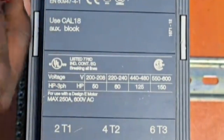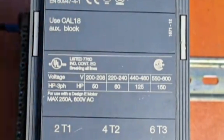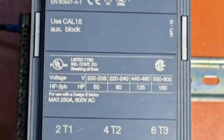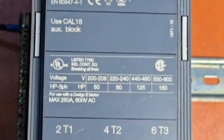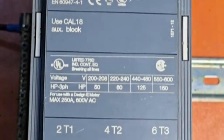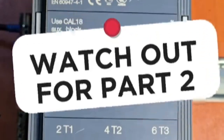All right, so down here we have different operational voltages on this row. Now, what this means is that at 220 to 240 volts AC, this contactor can handle 55 kilowatts of load. And this AC3 stands for inductive loads, like electric motors. All right? So when we operate this at 220 to 240 volts, it can take a load of 55 kilowatts.